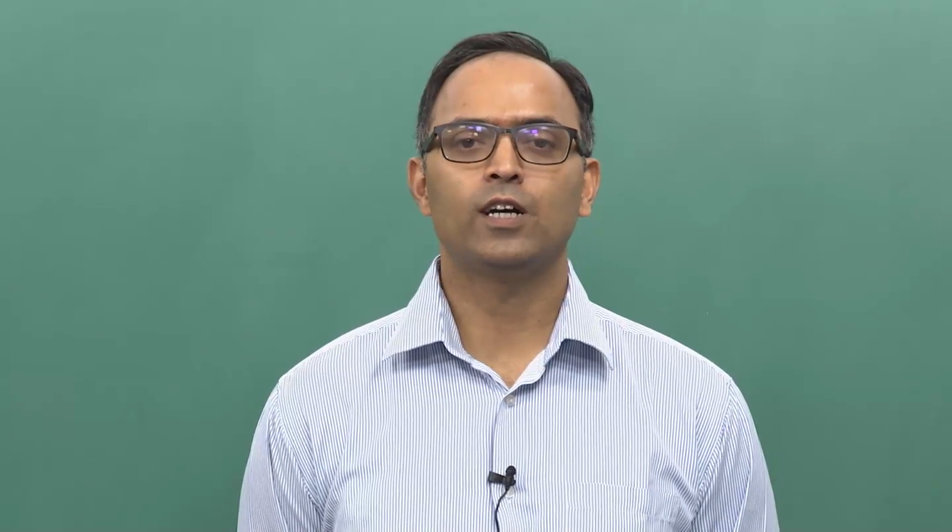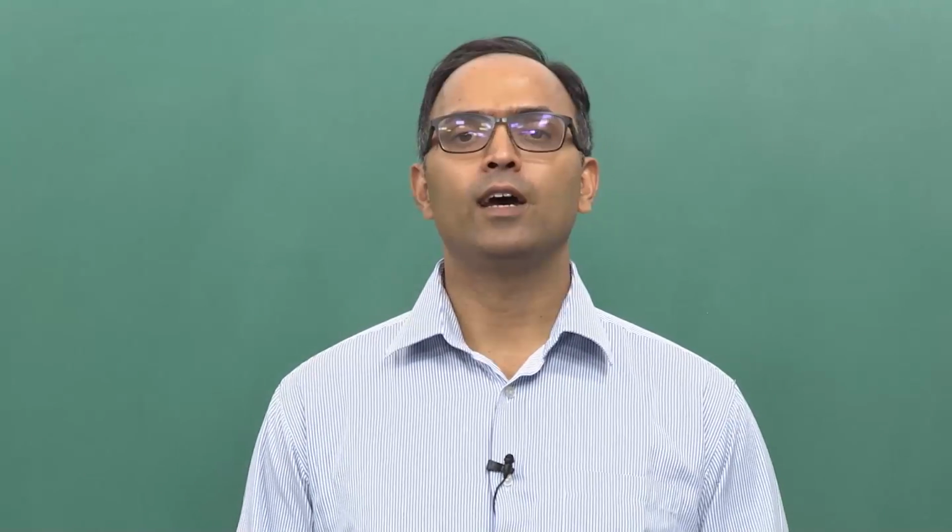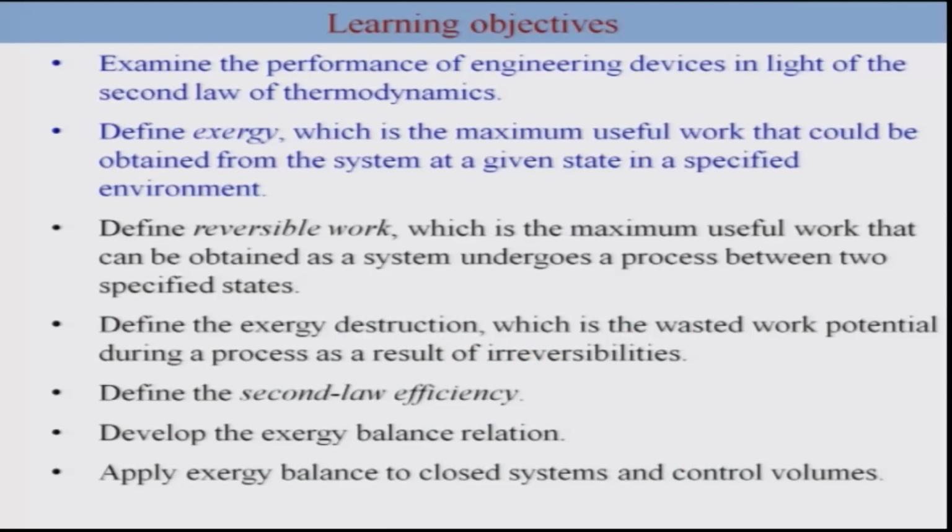Welcome back. We are going to start a new topic, and it's on exergy, and we'll examine the performance of engineering devices. Now, as we've already discussed, the first law of thermodynamics is concerned with the quantity of energy. On the other hand, the second law of thermodynamics mainly deals with the degradation of energy during the process, or is particularly concerned with irreversibility or lost opportunity to work.